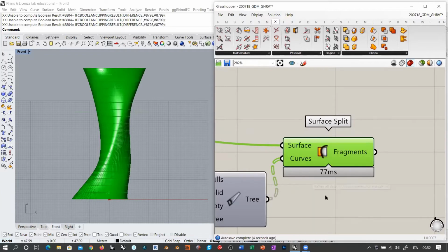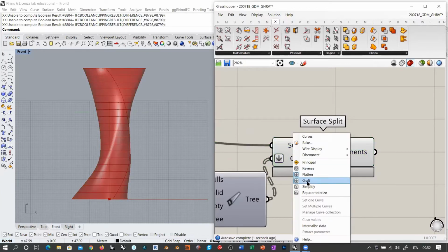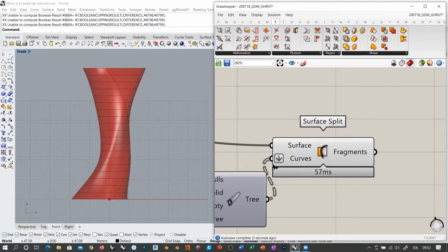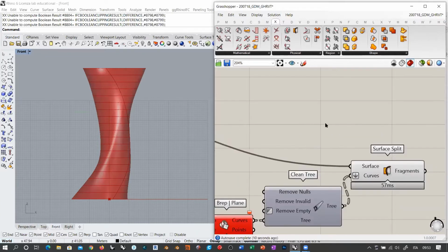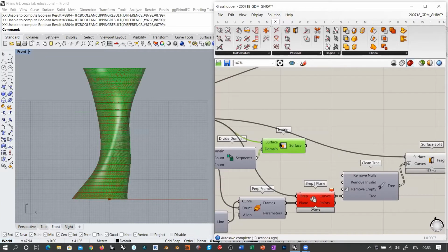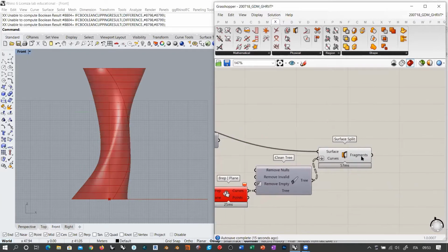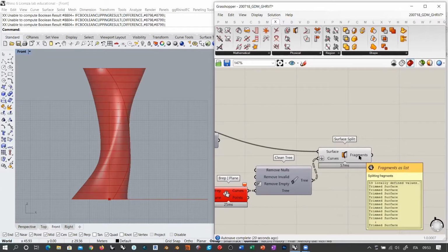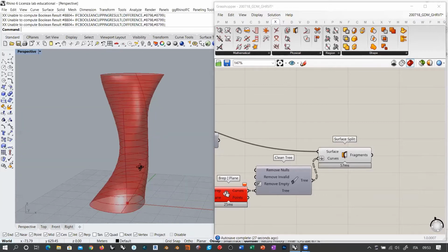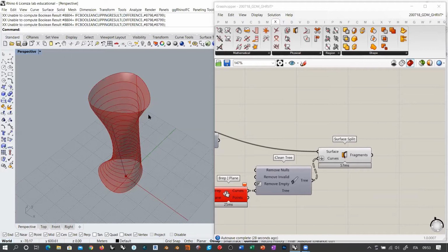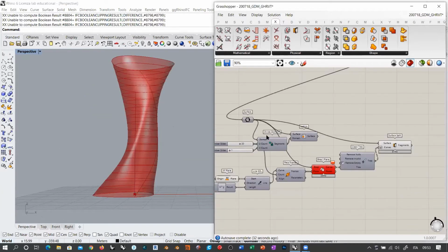Eventually, I think that grafting a data tree here would not be working. So we get here 19 fragments, which are the horizontal stripes. But in this case, they are not topological stripes. Okay, they are physical stripes. So they all have the same height. And once you have these fragments here, you can eventually then subdivide them horizontally, which is something that reduces the lack of control that you have with the topological approach.